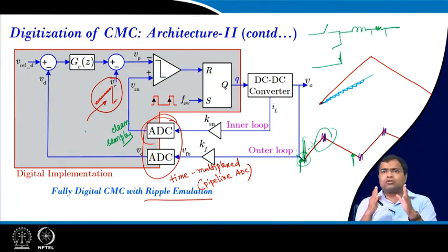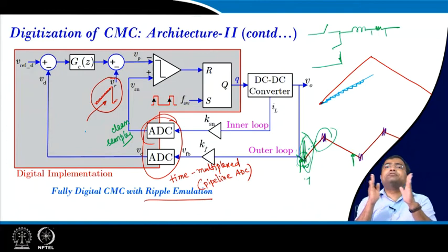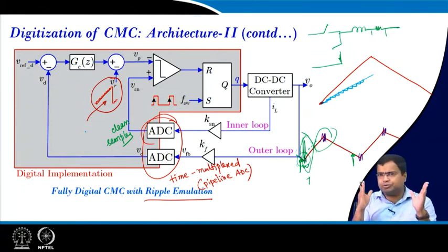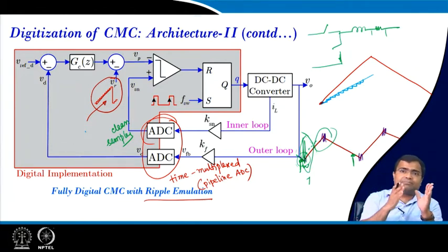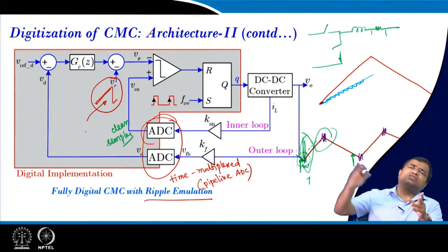So, in analog control, people use something called blanking. That means they do not take any action for a certain on-time duration, and only then do they compare. That actually limits the effective duty ratio operation. That means you cannot achieve a very low duty ratio operation due to this blanking mechanism. So duty ratio below 10% or 5% will be 0. It will start from 5% to the full swing.